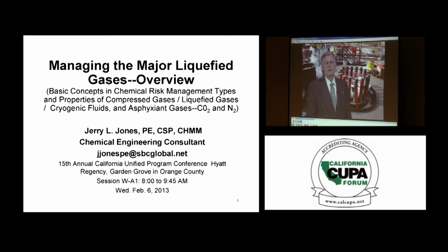The CSB case study on the Valero accident underscores the importance of strict safeguards when working around low oxygen environments. Workers are in danger not only inside confined spaces, but also around openings where inert gases, like nitrogen, are flowing out. Here's what we believe happened the night of the accident.